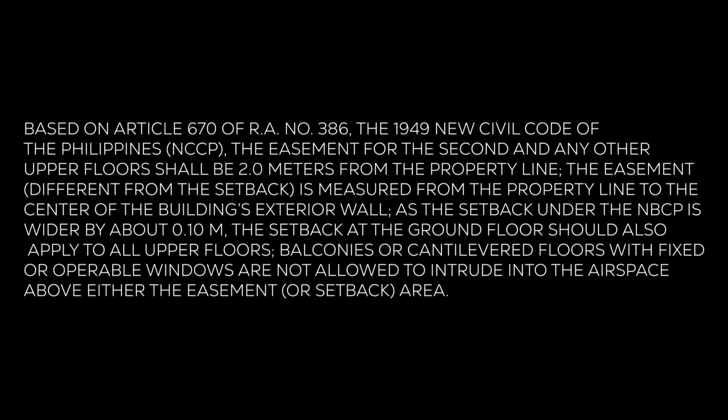The easement, different from the setback, is measured from the property line to the center of the building's exterior wall. As the setback under the NBCP is wider by about 0.10 meters, the setback at the ground floor should also apply to all upper floors. Balconies or cantilevered floors with fixed or operable windows are not allowed to intrude into the airspace above either the